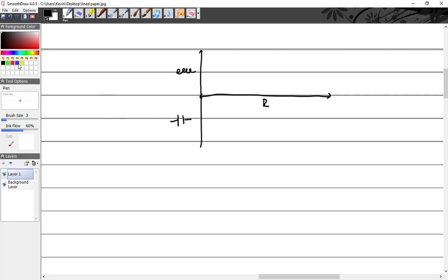You plot all of this, and you say, okay, I have this much resistance, and this much capacitance and this much inductance. You subtract the two, and just visually speaking, do I have more coil or more capacitor in my little plot here? I have more coil. So you subtract the two, and that becomes right there. Let's say that's my inductive reactance. So here's how much resistance I have, here's how much inductive reactance I have, and then you say, oh, well, here's my impedance.